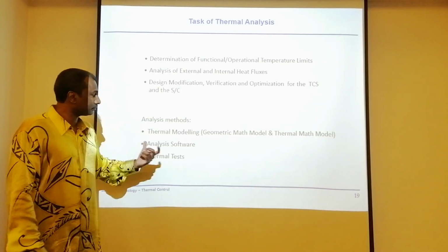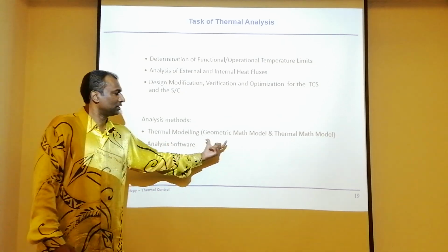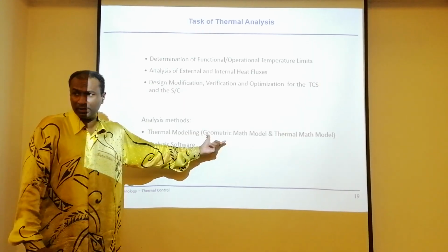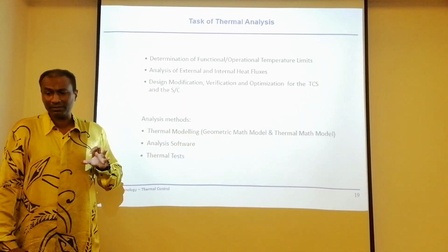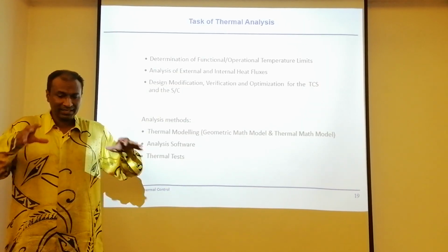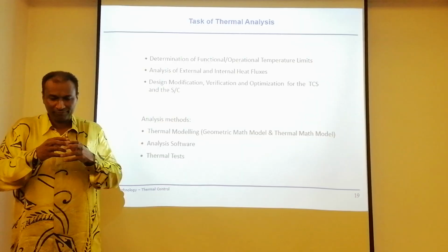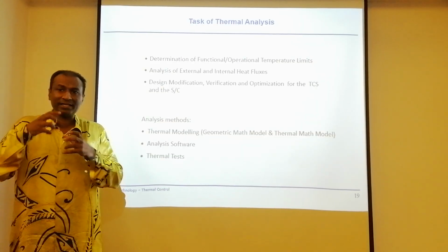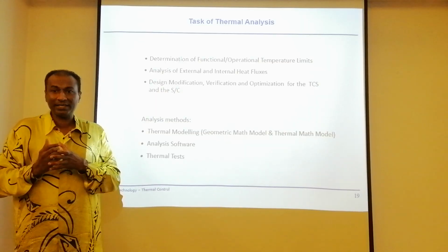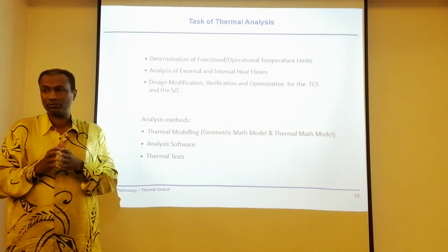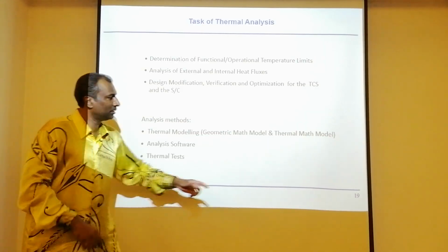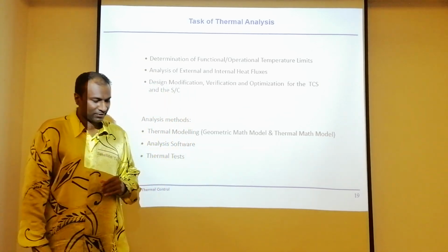Analysis methods: thermal modeling, geometric math model, thermal math model. The geometric mathematical model is very complex, and can be done numerically, because for each and every component of the satellite you need to generate its geometry, see how this geometry is looking at the sun, and then calculate or estimate the actual temperature generated by that particular component. The thermal math model is slightly simplified.